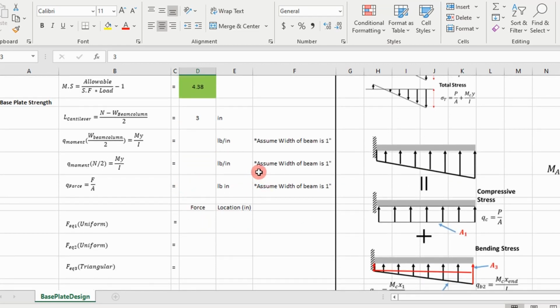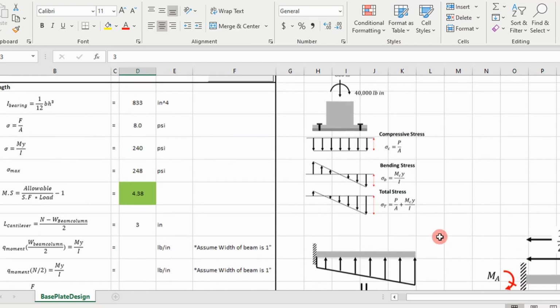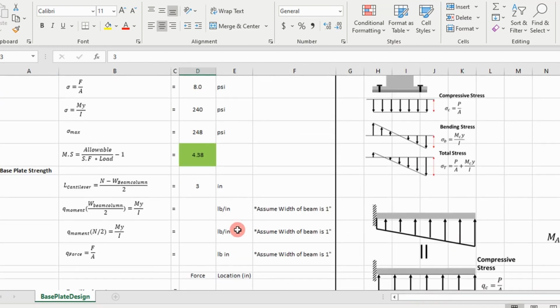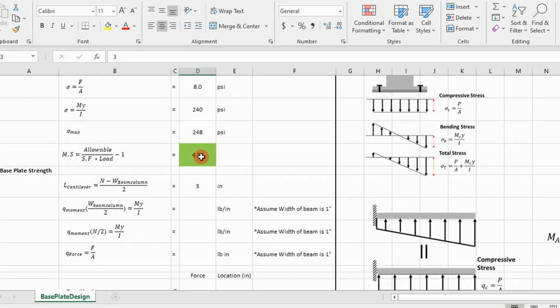And if you recall, if we treat our cantilever beam as a 1 inch wide beam, so you can see down here we treat the cross section as 1 inch wide, we can make a simplifying assumption that ensures we can convert the stresses that we calculated up here to line loads. That greatly simplifies the analysis. You can go derive that. It's pretty easy to do, but you can either derive it or believe me.